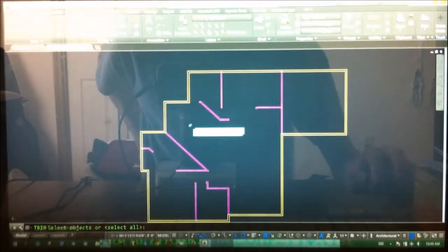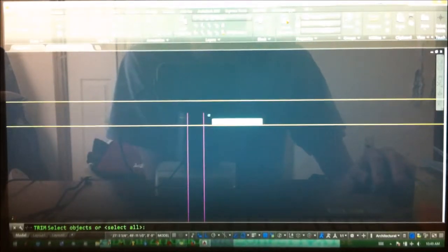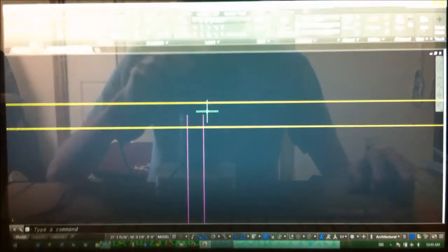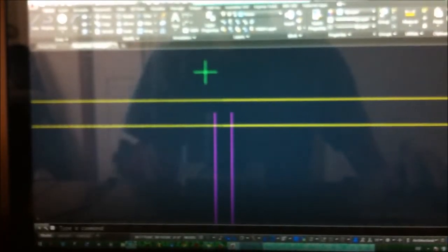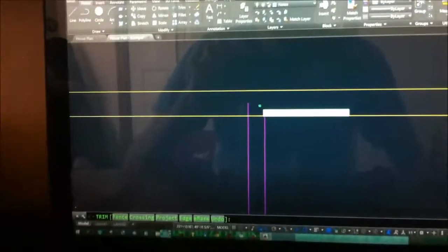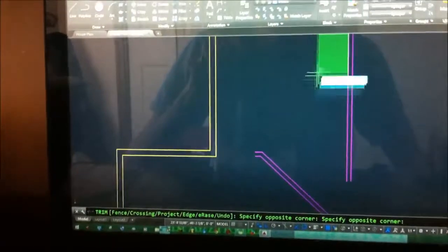Anyway, now you're going to have little lines like this that are going to go in here. What you want to do is trim. You don't want to fool around making a mistake trying to manually move that thing up to where it looks like it's all together, because you can easily mess something up. Just use the trim option. Click on it, then on the screen anywhere, right click, and it automatically goes into that option. Then you can just start clicking off on all your stuff.